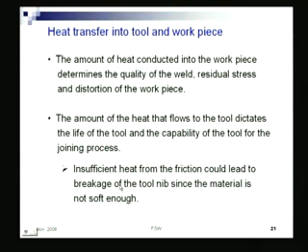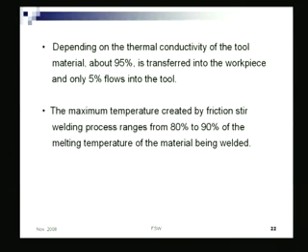Like in fusion welding, if the heat is insufficient, you may not have proper deposition, you may not have proper fusion. That means there can be lack of fusion, lack of deposition. But as such, to the welding equipment there is no damage, right? But here the welding equipment, the tool, will get damaged. So depending on thermal conductivity of the tool material, 95% is transferred to the workpiece, only 5% to the tool.